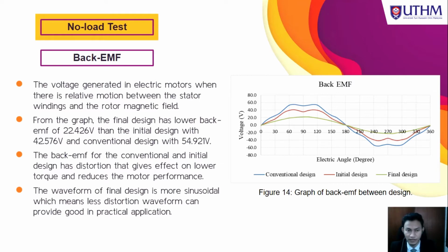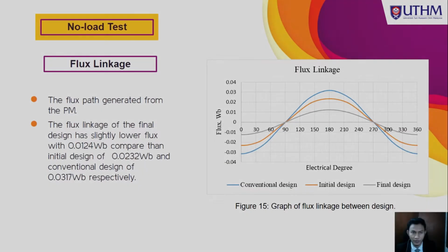Okay, for the final design, the waveform is more sinusoidal, which means less distortion, and the waveform can perform well in practical applications. Next, we proceed to the no-load test analysis, which is for the flux linkage.